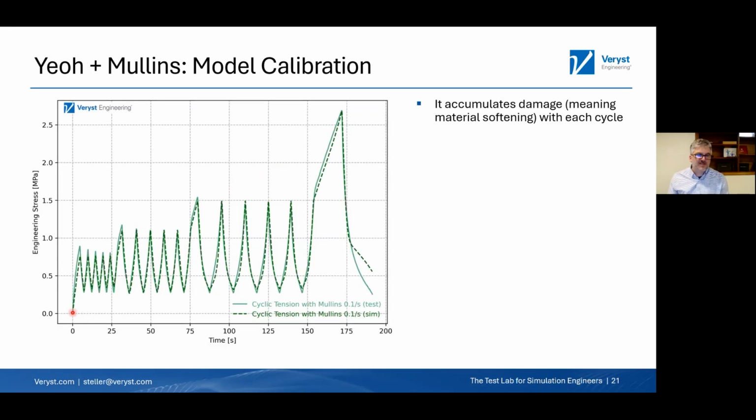So the way we calibrate this is we do a single element simulation, and it simulates up to, I don't know what this was, 5% strain. This was a strain control test. And then it unloads to this strain, and then it unloads to 5% and unloads and does that 5 times and goes up to the next one. So it does this exact strain history repeated over and over again, because those repeats will also help you dial in some of those parameters, and particularly the R parameter, and how fast you accumulate that damage that really goes in there.